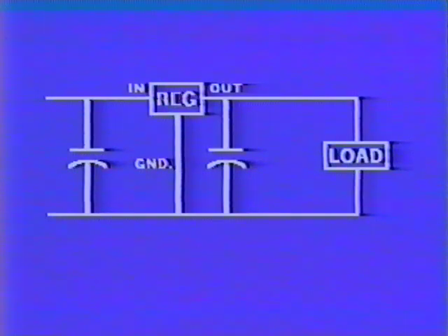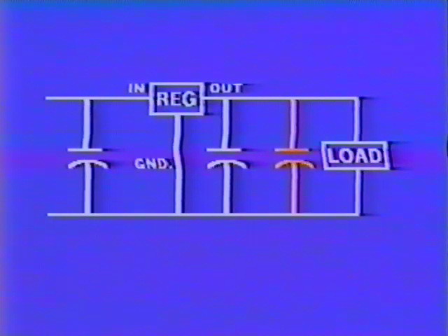Here is a typical 3-terminal supply. Notice that a simple capacitor filter is used, and that a small filter is placed across the output to help the regulator. It is not unusual to see a small capacitor in the range of 0.01 to 0.1 microfarads placed across the output of the regulator. This capacitor dampens high-frequency ringing that can cause the regulator to oscillate at 10 kilohertz or higher.